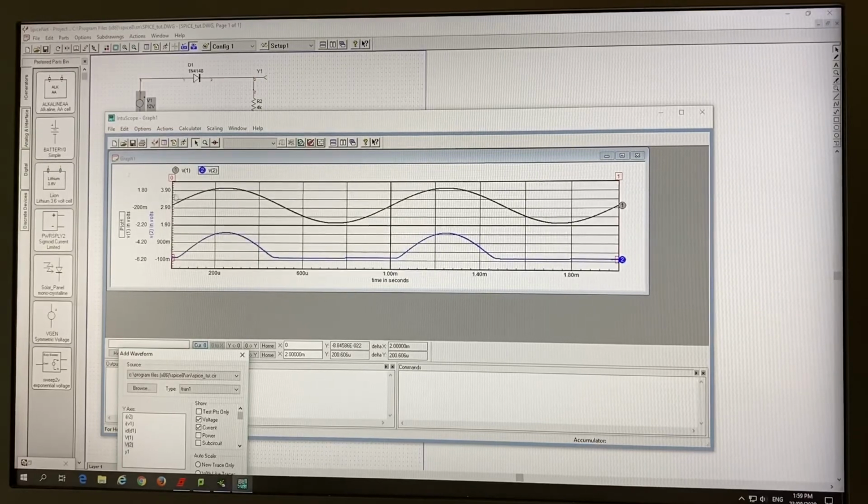Look, so when it was positive, I would get an output. When it goes to negative, at this point, my diode will not allow negative current to pass through. It will cut it off. Characteristics of a diode, right? It's a unidirectional component. It's unlike a resistor. If I was to put a resistor there, then measure voltage across the resistor, it will be exactly the same shape as the input signal, just a different magnitude. It will be V over R, my magnitude in that case.